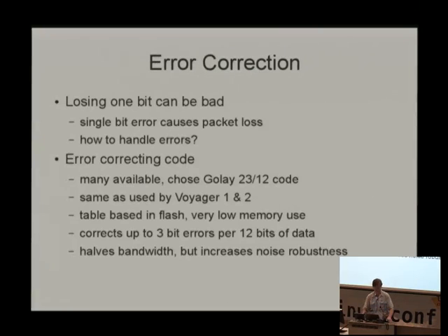Okay, so what about error correction? The next step is what about, we're sending, say, 250 byte packets. If you get one bit wrong, then a checksum over the packet will be broken, you'll lose the whole packet. And in fact, that may contain dozens of Mavlink packets, and that's fairly bad to lose that. So what you really need is an error correcting code. And you need to be able to correct bit errors.